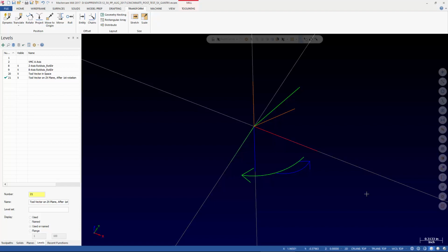And by rest of the stuff, usually it is setting the rotary axis limits, setting things like primary angle output and secondary angle output options, whether you allow positive numbers or not, those kinds of formatting questions. But really, this is the heart and soul of the post right here. Using the M-type variable, setting up rotary axis direction and rotary axis, basically.